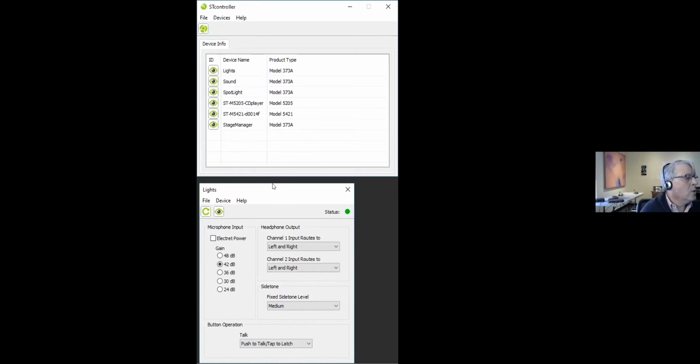What can you do with each belt pack? And what I find interesting about this is a small, simplistic belt pack, right? Not terribly expensive, works very well. You have a lot of control over what you can do. You can turn on power for a mic. Some headsets need 5-volt or low voltage power. You can set the gain of the headset. That can match the microphone, or it can match a user who speaks very loudly, or someone who is in a position out in the audience and they have to whisper. You can crank up the gain.